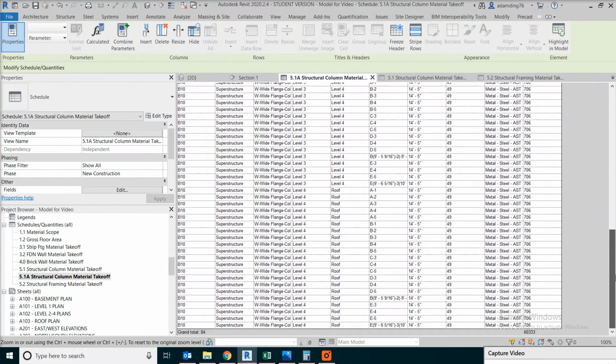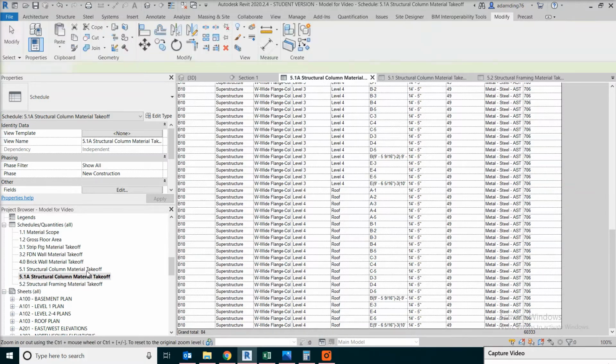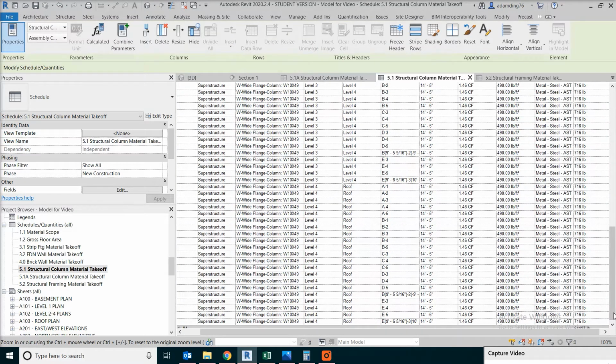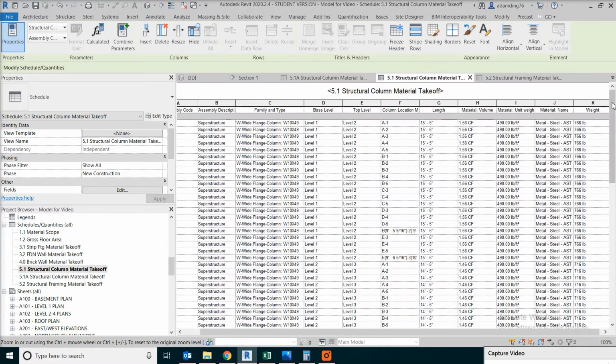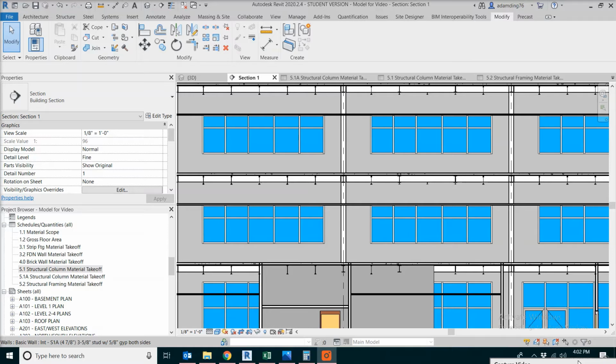The total weight of the columns we have is a little bit over 60,000 pounds, which is quite close to the number we had before by using the volume and density method. Now, the same approach can be used to calculate the weight for the beam. Pick any beam, repeating the same procedures we had with the column.